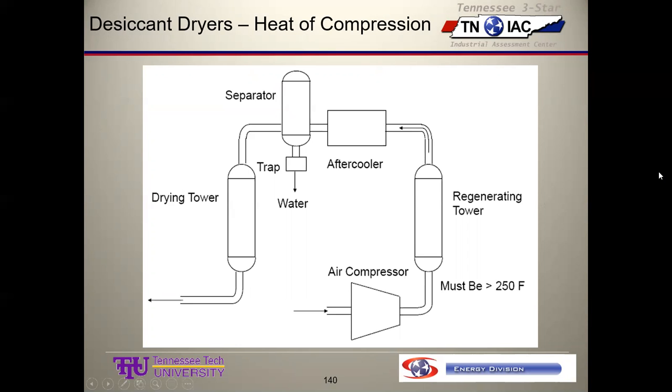So if you're going to buy a new heated compression dryer, you have to kind of rework your compressors because your compressor's set up to have that aftercooler right after the compressor. Most people that have these bought a new compressor dryer package and it all came together constructed as one unit. But this is how the flow goes. We come out of the compression element and the note is we've got to have 250 degrees at least.